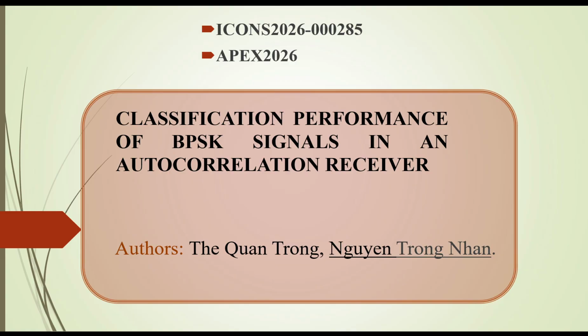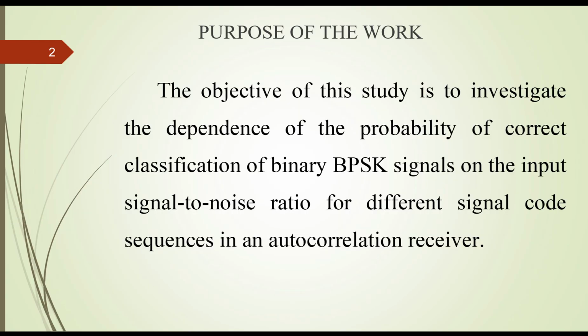When conducting radio monitoring in a complex electronic situation, an important question is determining the type of modulation. Unlike radioelectronic means of location, navigation, and communication, for the means of radio monitoring the parameters of the signal are a priori unknown. Therefore, their optimal processing is possible using an autocorrelation receiver.